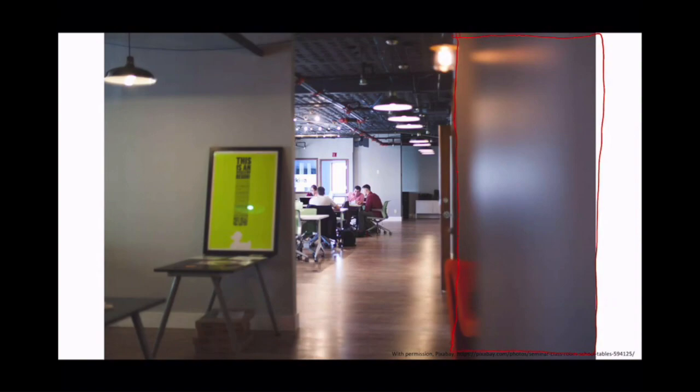Normally we would say a storage area has to meet a higher threshold. It's more restrictive in the code because of all the content that could burn. But in fact, if we meet those two criteria, we have a B here, business for the accountant's office, and we have an S on the other side of this wall for storage, but we don't have to consider the secondary occupancy really too much. I'll explain in a minute.